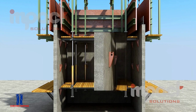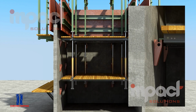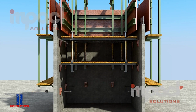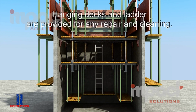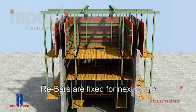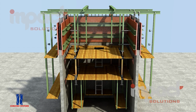The moved upper brackets are clamped and secured, the open cylinder is closed, and the lower bracket is moved up too. When the workers reach the new floor, the system pauses for the concrete pouring process. After the concrete has hardened, the hydraulic system is reactivated to move the entire formwork and climbing bracket upstairs. This process is repeated and the building gradually rises.